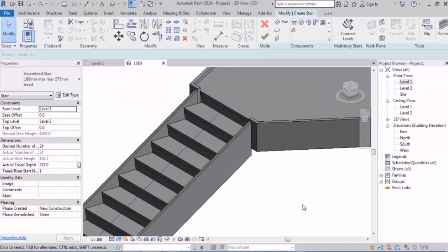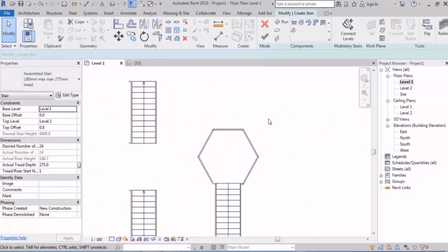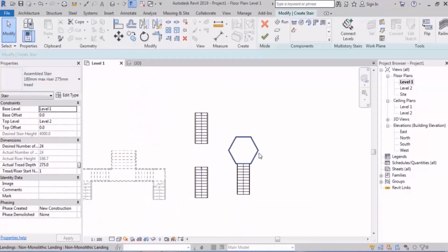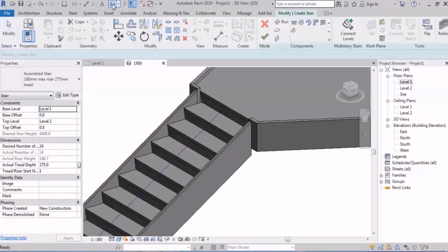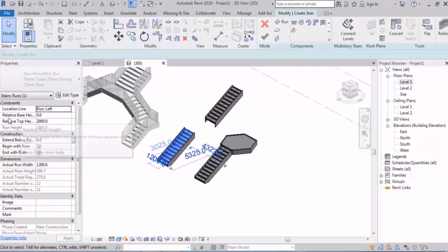Now they have a connection, but before that you need to check it. I told you some methods. You check it to make sure that there is connection. And now we are sure that everything is okay. Also remember that while you're drawing your stairs, they must never have the base offset. Well, of course, the stairs of the first ramp. The second ramp starts from a different height. But generally, the stairs must not have a base offset.